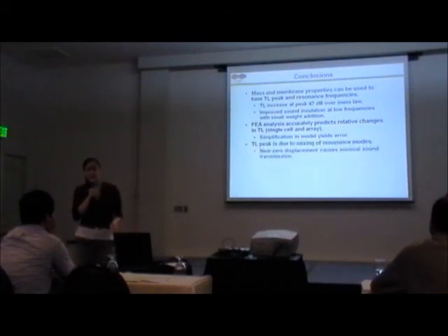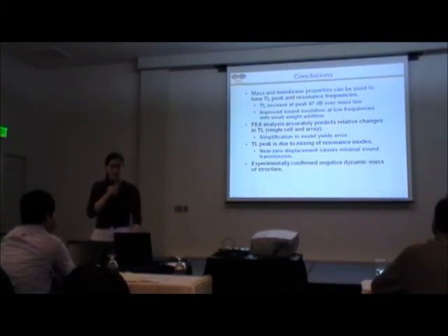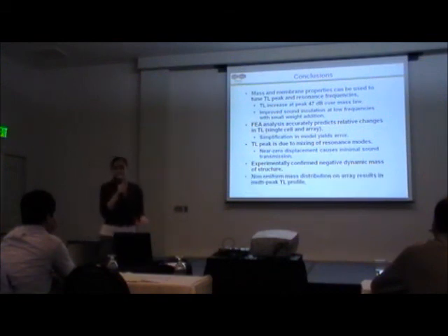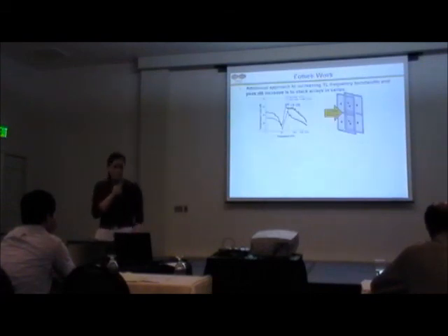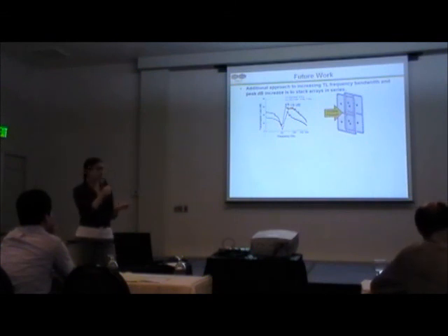We were able to determine that the transmission loss peak is due to a mixing of the resonance modes, and that near zero displacement causes minimal sound transmission. We were able to experimentally validate the dynamic mass, or negative dynamic mass, which has been predicted by other researchers. And we were able to determine that a non-uniform mass distribution on an array will result in a multi-peak profile.